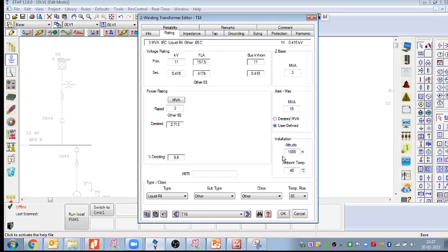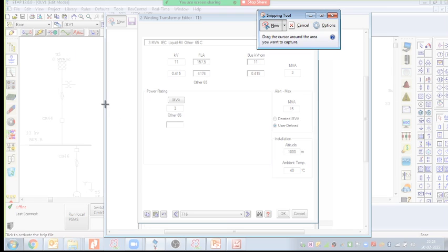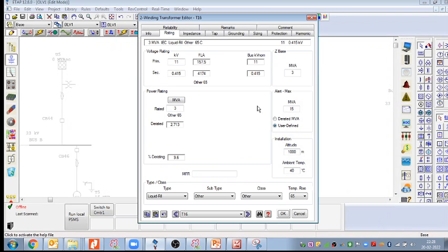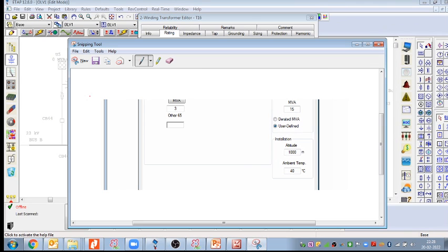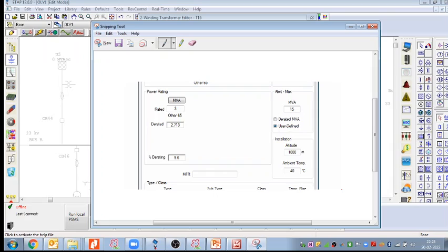So what is my important conclusion? When you review the equipment drawing, when as an engineer you review the equipment rating, this rating plate, the technical data sheet, please focus on the altitude they have mentioned, and please check that against your project altitude.